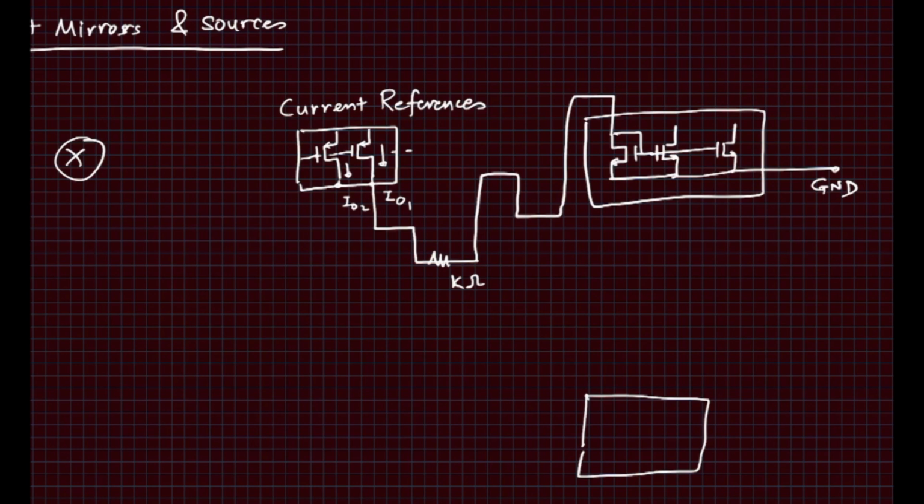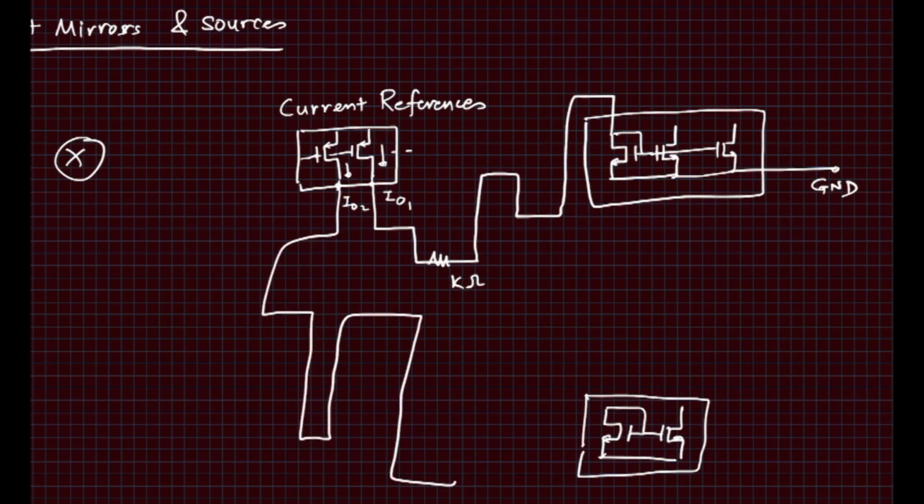You could have another current mirror at the bottom over here, which would have a bunch of matched transistors, so we can replicate the currents. This path could again be long and winding depending upon what comes in its way, and it eventually lands up here, and there could be a different ground connection, ground 2, on the chip. Once you design with a proper ratio, the IO1 and IO2 relationship should stay intact, and then locally these currents are mirrored over here, and they should match very well with each other.